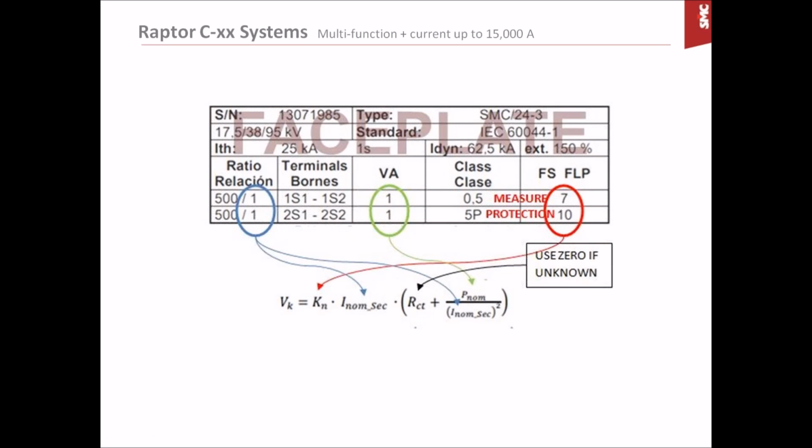Okay, so we can set this value here and then calculate this ratio here, which is the nominal primary, okay, and the nominal secondary squared. So from this simple equation, you can approximate the expected value for saturation voltage. In this particular transformer that we are using in this example, the voltage is evaluated by this formula as around 30 volts.